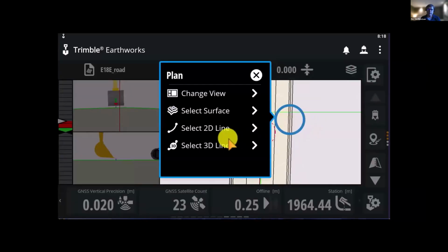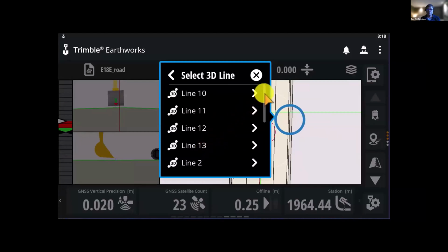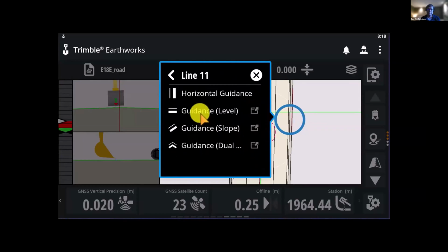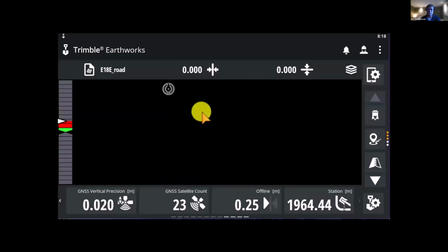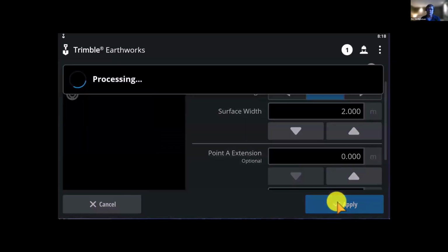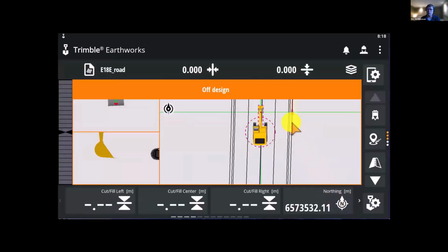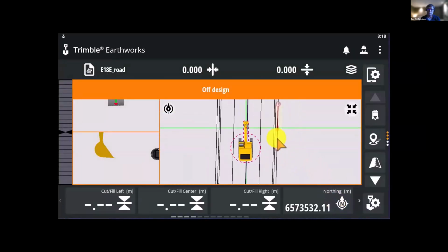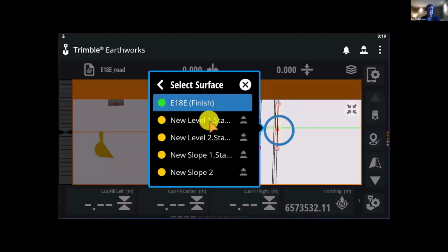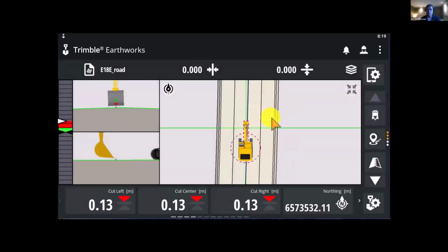Then if you click on any line, you will have the possibility to select the lines that came from Quadri directly in here. If there was a naming on these, it will appear with a name. And you can also use these lines as guiding and create a design inside the design and use only that. So like sewer lines or water drainage across the road, you can select those and use them in addition to your machine control design and surface.